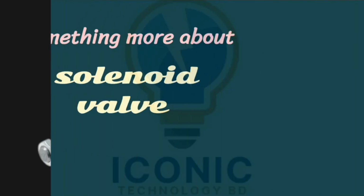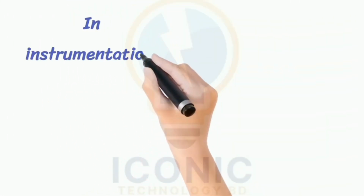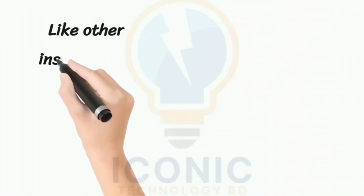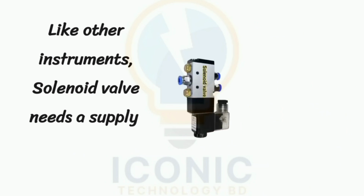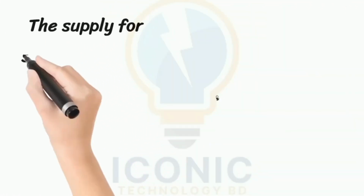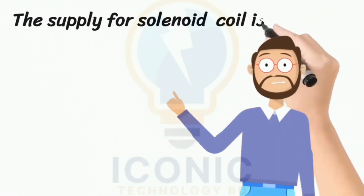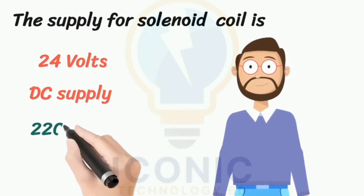Let us understand something more about solenoid valves. In instrumentation, solenoid valve is also called SOV. SOV is the short form. Like all instruments need supply, similarly, supply is also required to operate solenoid valves. The supply of solenoid valve is given to its coil. Mostly, only two types of supply for solenoid coil are used: 24 volts DC supply and 220 volts AC supply.